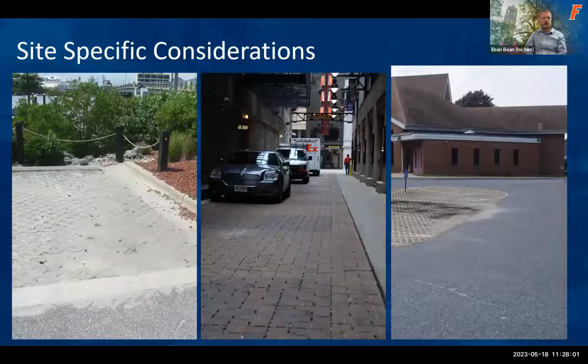On the left, we've got a coastal permeable pavement system where there's a lot of wind-blown sand, and obviously they haven't been keeping up with removing that sand from the surface, so we need to think about that and account for where that sediment's coming from. On the far right, we have a church parking lot with a very high impervious to pervious ratio. Essentially you're focusing all of that runoff and all of the sediments generated off that pavement into this narrower, smaller area. So it's important to keep that in mind when projecting for maintenance, and to consider what that ratio of impervious to pervious area is.